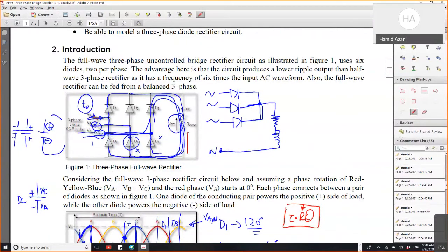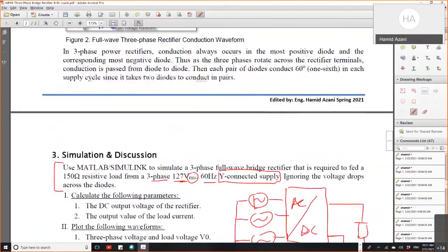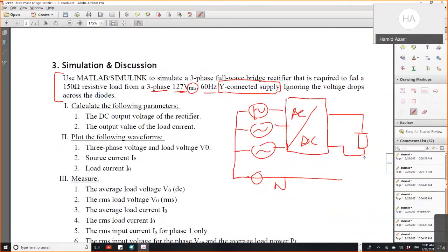Here I told you this should look for the other phase to the current. The current coming from here should look for the lowest phase, not neutral. If we do the neutral, nothing will work. If I connect here to the neutral, I'm bypassing the diodes, and the current will be going from the other side to those phases. So this is not to be done.